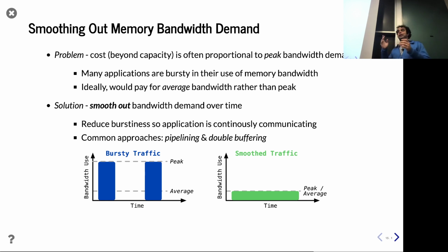And so if you take the average number of cars that get through Highway 1 over a day and divide it by the number of hours in a day, the cars per hour may not be very high. So you might say, oh yes, 2 lanes per direction is perfectly appropriate. But the reason why that fails is that people don't travel in a perfectly uniform manner. They travel in a very bursty way. They have rush hour or whatever else they're doing. And so that bursty demand can cause problems.